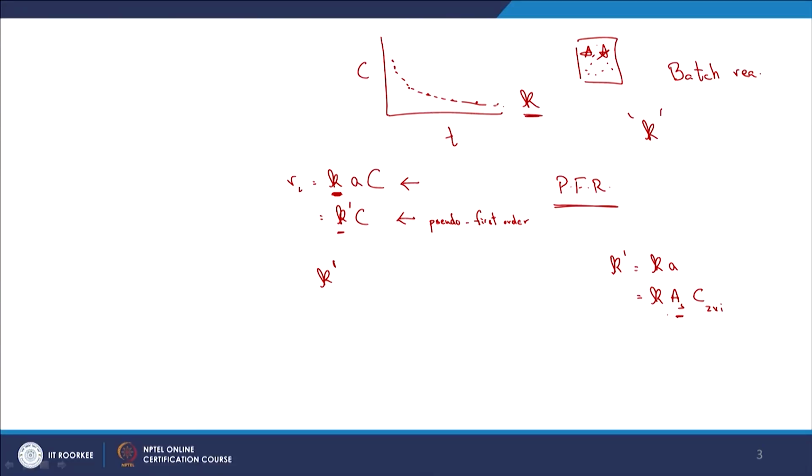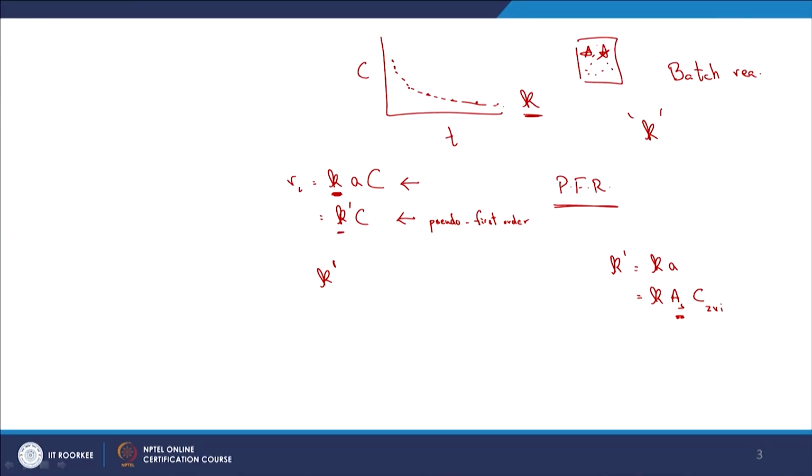So, if you use different kinds, the surface area per mass of zero valent iron will be different, right. Let us say a simple example, because it is relatively cheap, let us say I get some particular bigger size particle for my particular lab experiment, but in the actual PRB let us say I use relatively smaller size particles. So, in that case the specific surface area is going to be different, right, because the surface of the zero valent iron available per mass of zero valent iron is going to be different, and so you can't directly use that K dash from the lab in the actual field or for the actual field design. You will need to be able to adjust that, right.